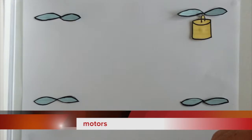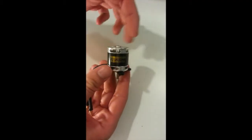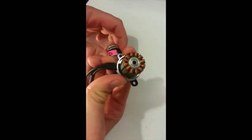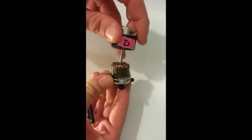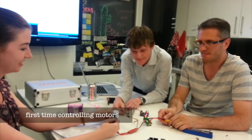We will be using brushless motors to rotate the propellers. A brushless motor consists of a case, a shaft, and a series of electromagnets. A propeller will be attached to the shaft. Turning the electromagnets on and off really quickly will cause the permanent magnets attached to the case to rotate around it. Can you change the speed?